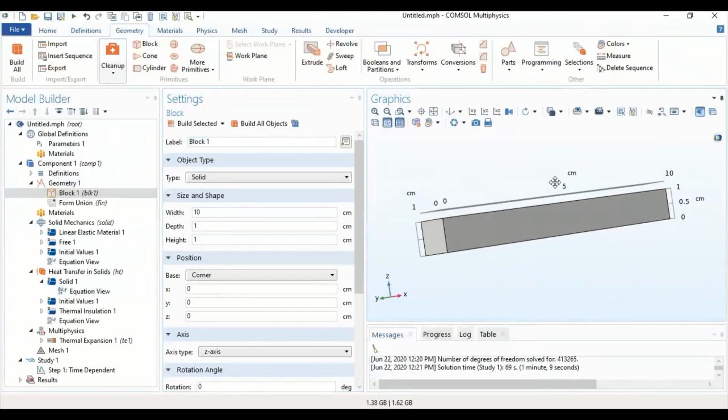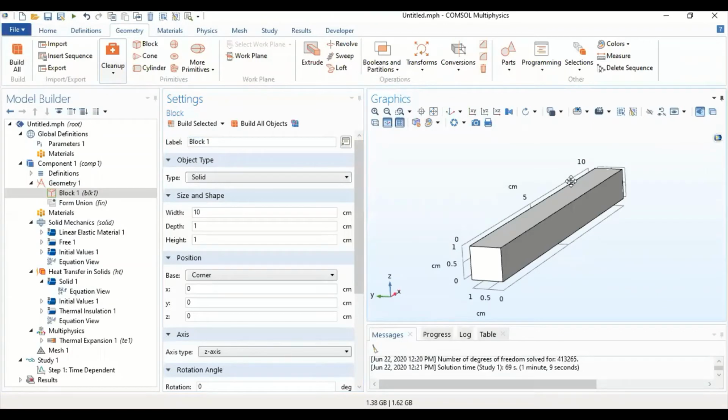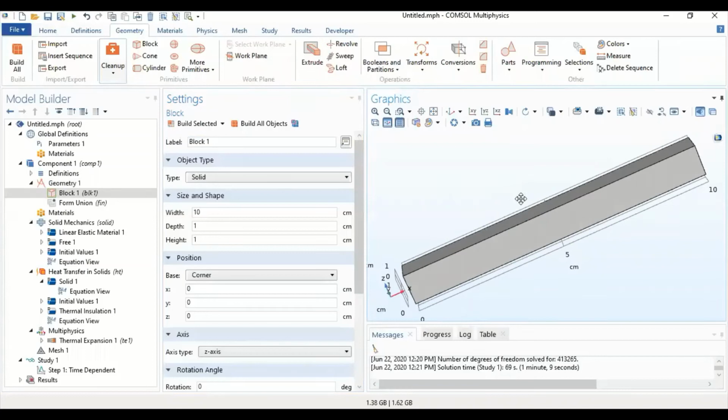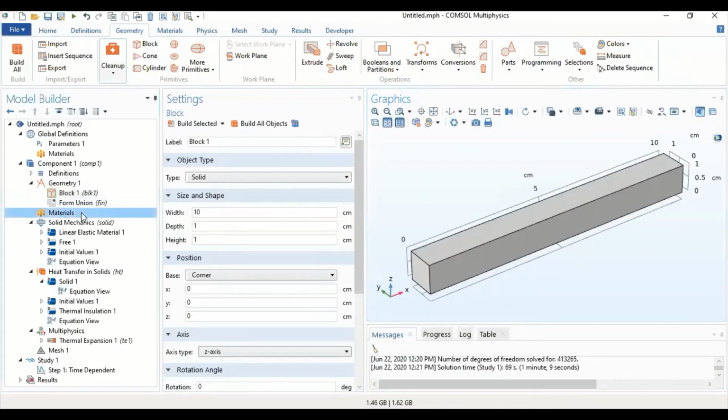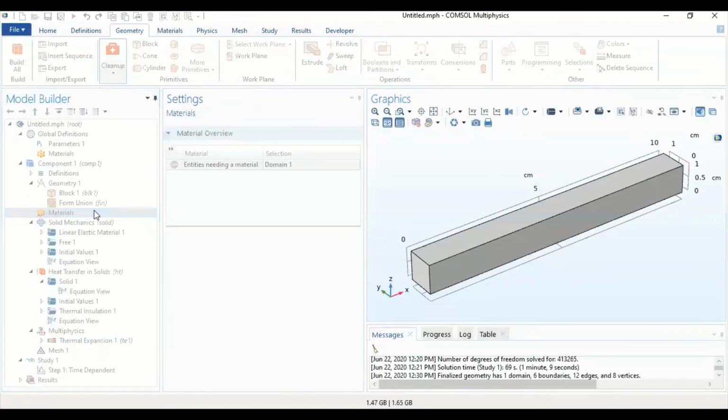This geometric member, we're going to apply a boundary condition for heat from one part and see how the heat transfers throughout the whole body. And also we can see what kind of thermal expansion or deformation happens to the body. For us to do so, there are multiple things to consider. First, we need to affix this body to a certain anchor or reference point, either a floor or a wall or anything.